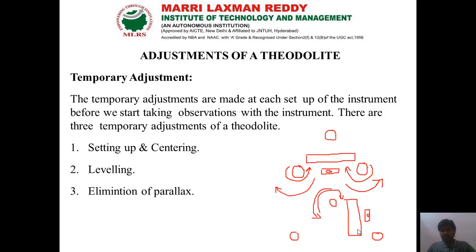We do this process alternately, so that the bubble stays exactly at the center position through all rotations. This we have to ensure, and that process is called leveling.